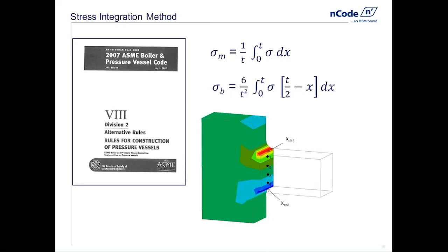But these are equally spaced locations where we can have DesignLife go in and interrogate at that location, which element am I in? Once it knows the element, it can go off and specify, well, where am I in that element? And then once I know where I am in that element, I can ask, what are the stresses? And we can calculate then at each one of those locations the actual stresses.